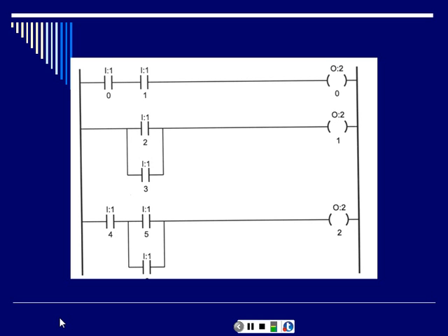Okay? I'm just going to say this one, so I'm going to say that this push button is a green push button in the supervisor's office. I'm just looking for something to identify it. So now, if that one's not working, I go to the supervisor's office and do the same thing to that push button, see if there's a problem. If there's not a problem with either one of those two push buttons, then I've got a problem with my output. But those are the only three things I would have a problem with if something else is working. And I need to identify those to know where they are.